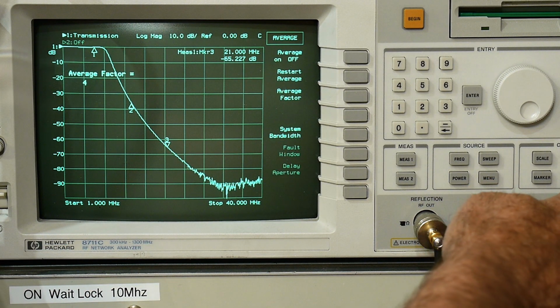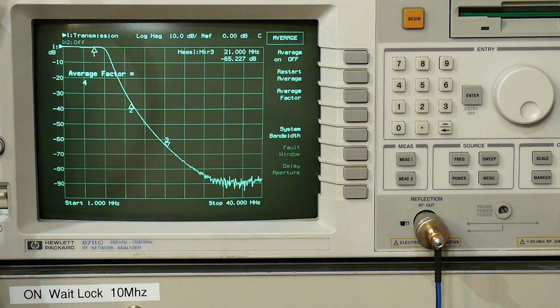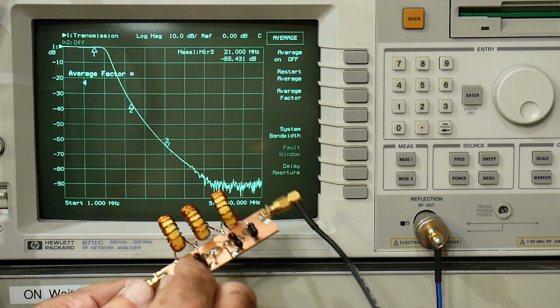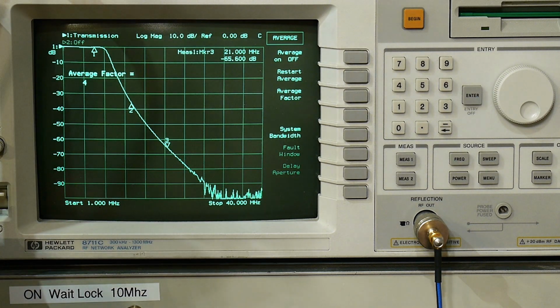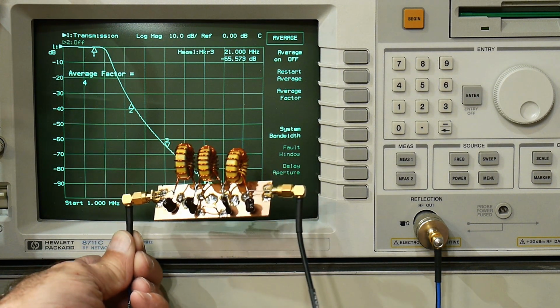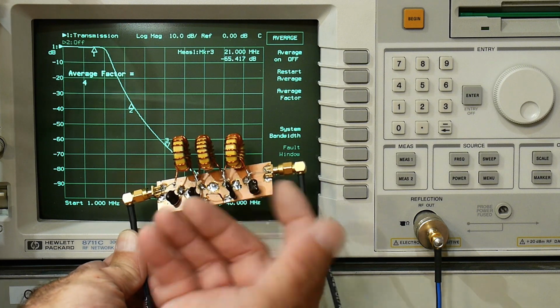And then let's see, we have no averaging on. You can see that our noise floor went down 5 dB just by getting those two capacitors out of the way. Let me bend them a little bit farther. And look at that. So this just shows you, it's down at minus 100 dB now. Okay, all I did was move those capacitors maybe a centimeter apart, maybe 8 millimeters.